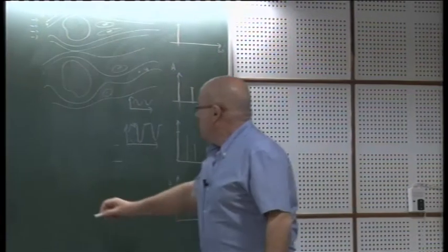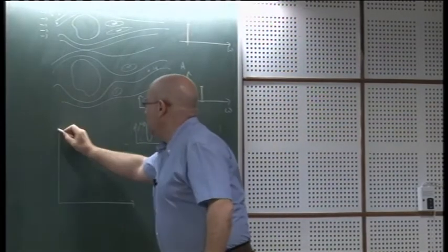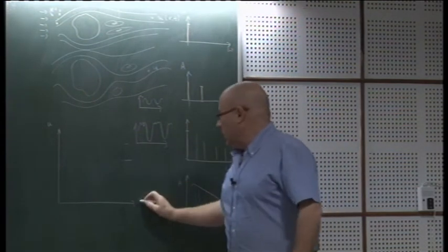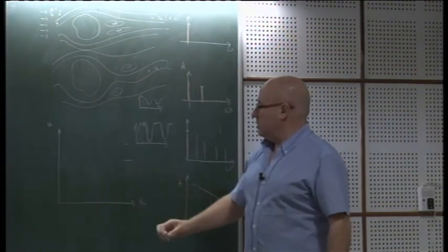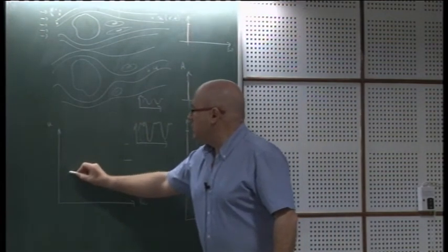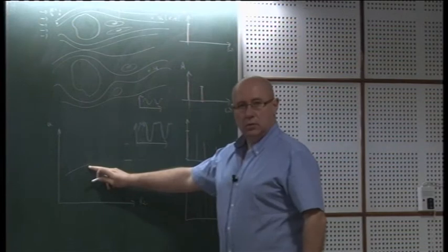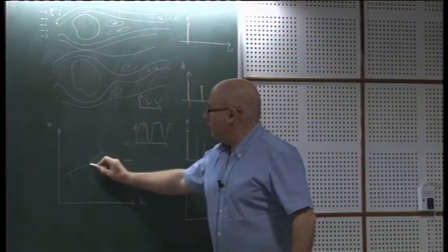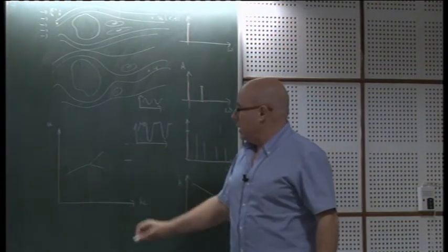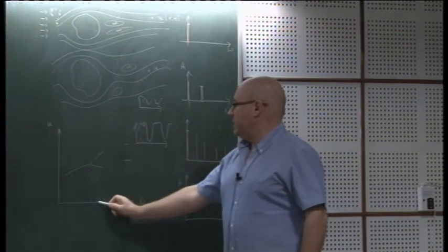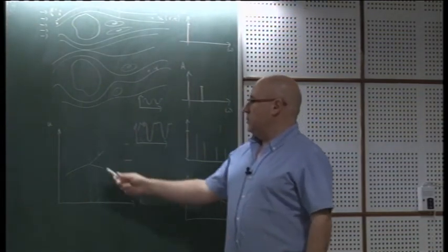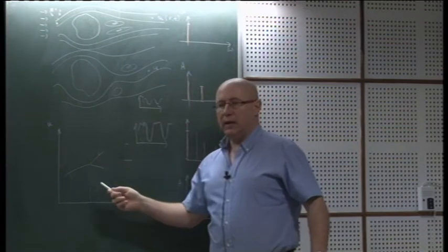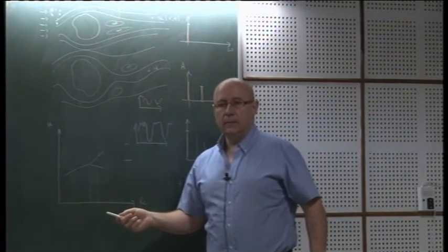You have probably seen that. So usually you could plot the solution space, which is a very complicated space, of course, in terms of the Reynolds number, just as a representation. For all Reynolds numbers, there exists a unique solution, in the long term, I mean. And then all of a sudden, you have a bifurcation. What does it mean that we have two solutions for the same Reynolds number? It means that the solutions depend on the initial condition. Of course, we will go through one path or the other path, depending on the initial condition. You understand what I mean?